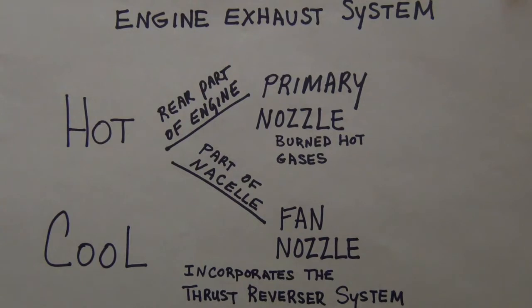The structure that you see with thrust reverse cowls has those special seals to protect against fire. Basically, again, it's keeping any engine fire that might be there in the turbine case away from any of the thrust reverse components, including your engine strut, fan, because remember, the thrust reverse assembly is all attached on the engine fan frame, so it needs to protect all that area.